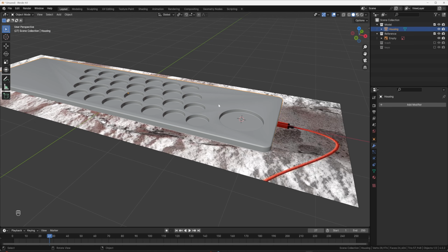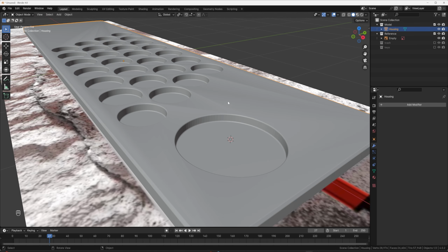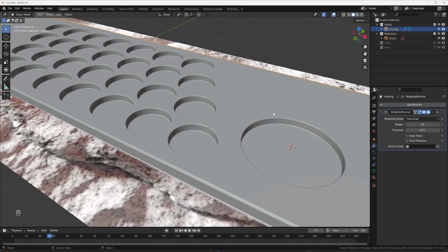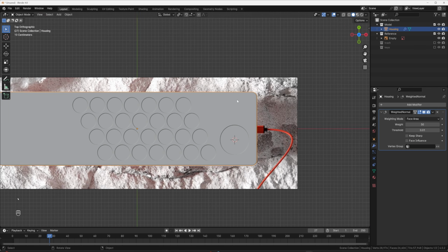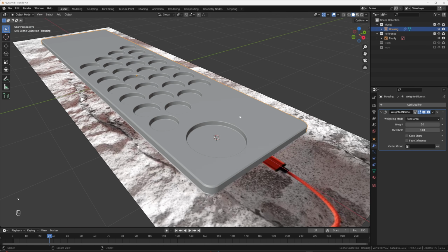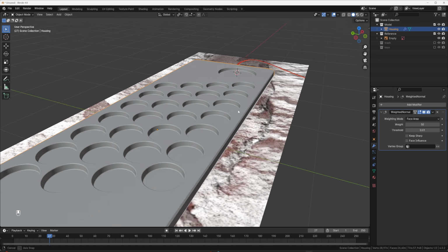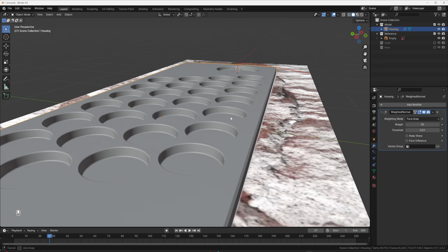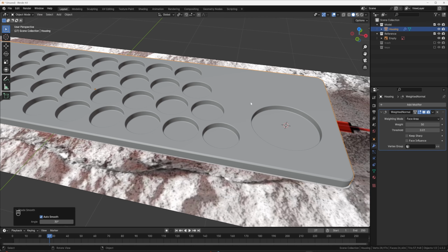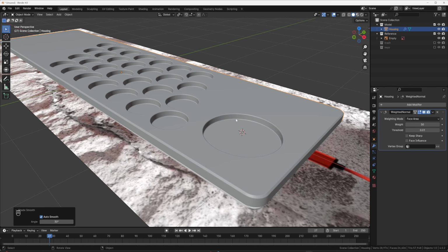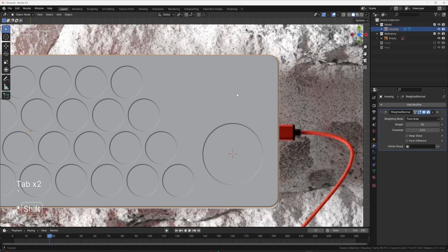And then it looks like we lost our bevel modifier or our weighted normal modifier when we did this. So I'm going to right click here, click W, weighted normal. And now we're right back where we need to be. We're going to have to probably do that again on this area, but I just wanted to show what the process is for those. So now you've got nice beveled edges. I think we are shading smooth, but even with these cutouts, some janky lines coming across, you still get good shading.